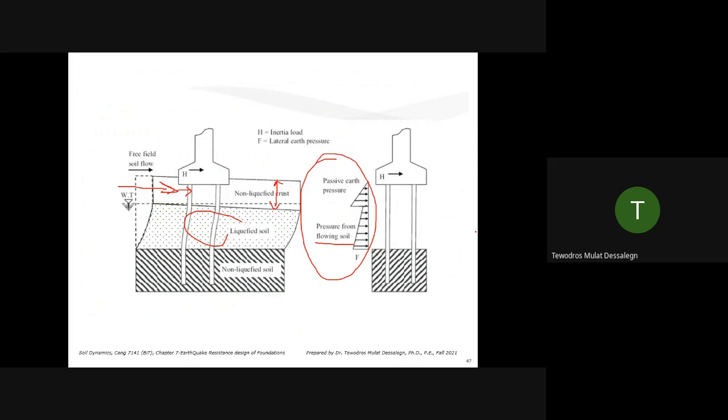So now look at it. You don't have any resistance. The pile is socketed in the bedrock, but now the kinematic impact is huge. So this pile section may be too large to design, but in this case, that's where we use battered piles. So they'll take out the lateral component. Still the inertial component at the top, you'll have all forces, vertical, moments, you design it for that. But in addition to all that, now you will design it for this additional kinematic effect.